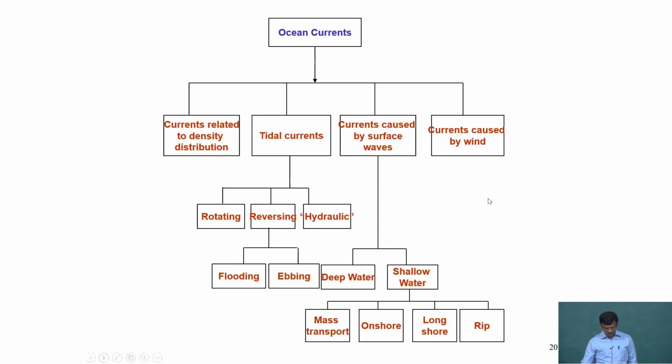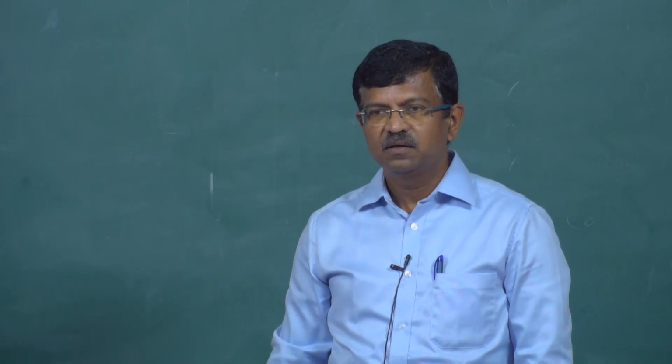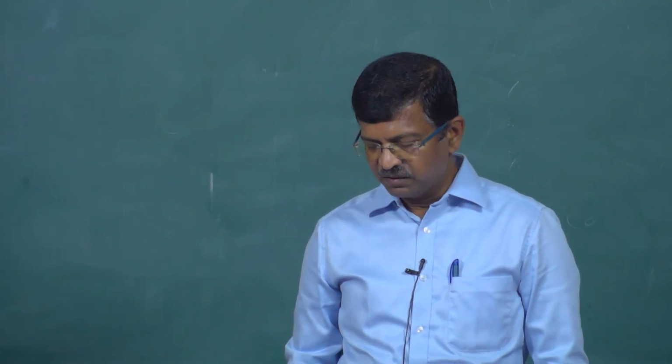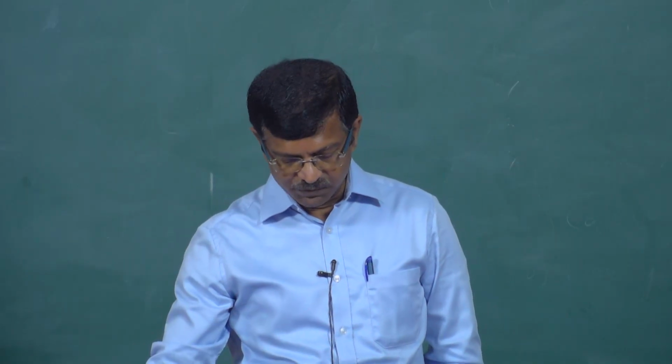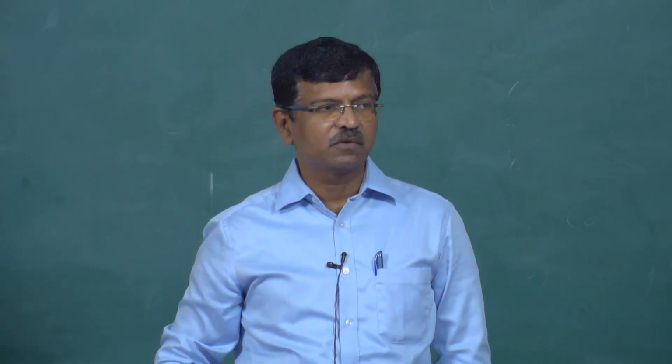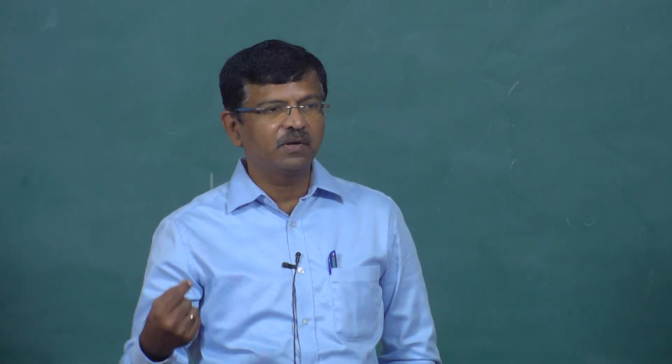There are many other classifications, which are just for your information, but what is very important for sediment transport due to waves is again the shallow water. I am interested in the near shore region, where there is a current that makes the mass transport, and when the water is drifting at the free surface, that means there is a mass transport in the wave propagation itself. Then there is the alongshore current, that means current moving along the shoreline, and the onshore offshore current, also called the cross shore current, where the current particle moves perpendicular to the coastline.